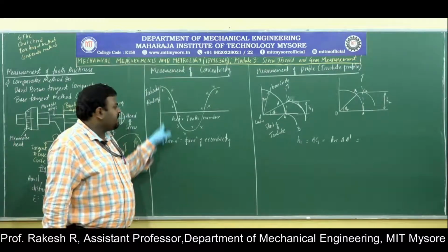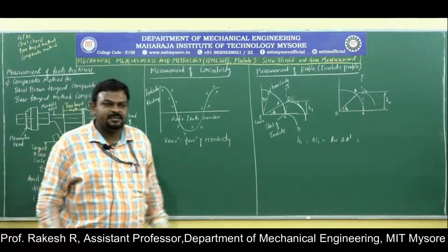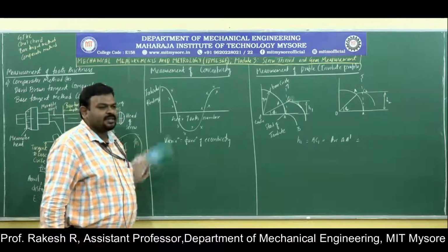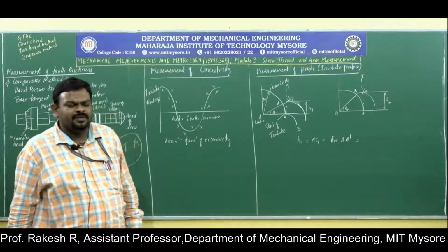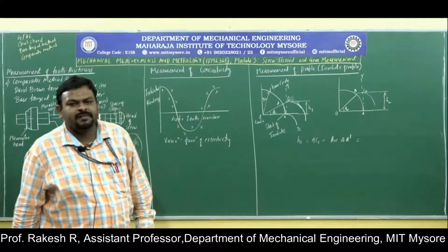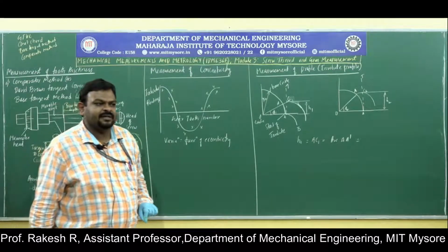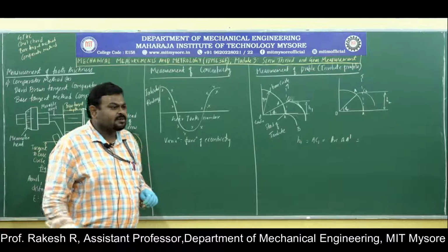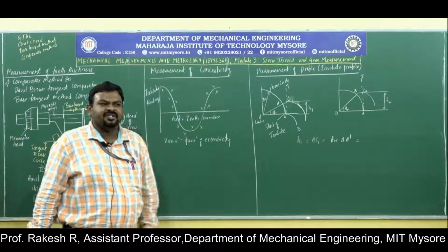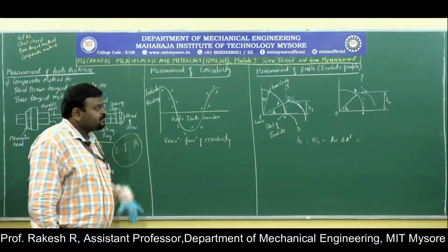So what is the variation here? That variation will be a function of eccentricity. Eccentricity means there is some offset from the center. We will be calculating that, which is nothing but concentricity. Concentricity is not a big parameter. Moreover, runout is a big parameter. Runout itself will indirectly tell us the concentricity in gears. So in most cases concentricity is measured like this only. It is an average curve. There are no such formulas, it is just a normal distribution.